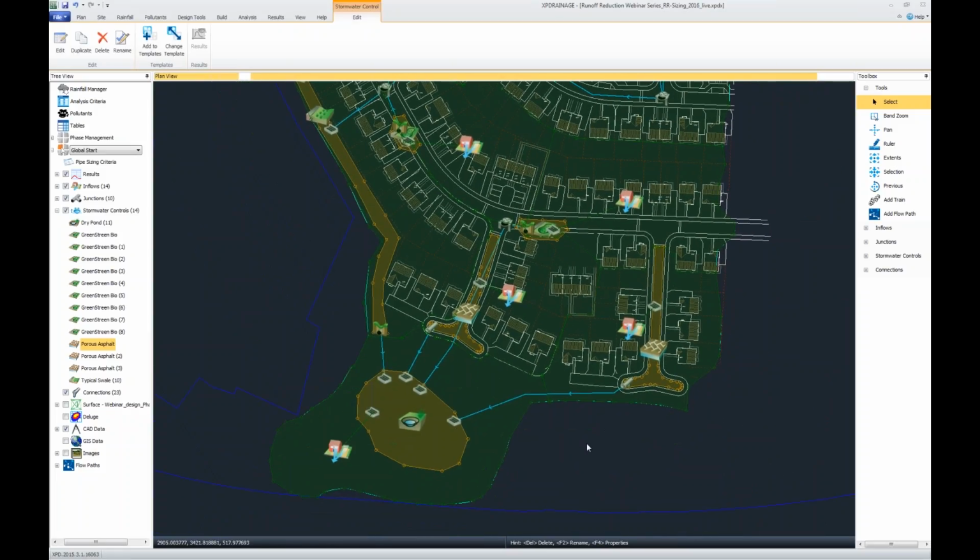So all in one go, we can see how far off we are, how well that design worked, or perhaps just adjust those constraints, maybe make them deeper. If you have a lot of swales, perhaps, which can be deeper, maybe underground storage facilities. Very quickly, we can design based on our site constraints.